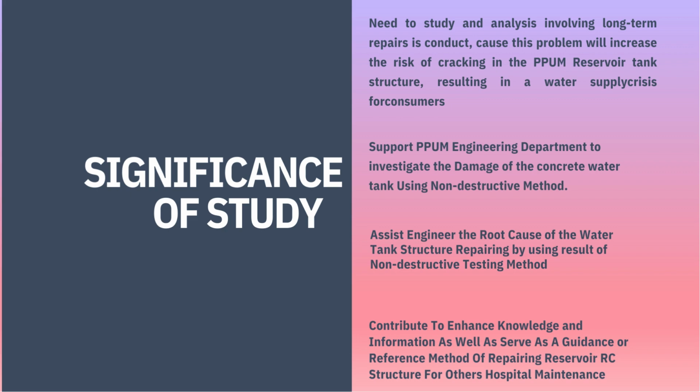So the significance of the study: there is a need to study and analyze, as a long-term repair is conducted. This problem will increase the risk of cracking in the PPM reservoir water tank, resulting in a water supply crisis for consumers. Second, to support the PPM engineering department in investigating damage of the concrete water tank using NDT methods, to assist the engineer in finding the root cause for the water tank structure repair using the NDT test results.